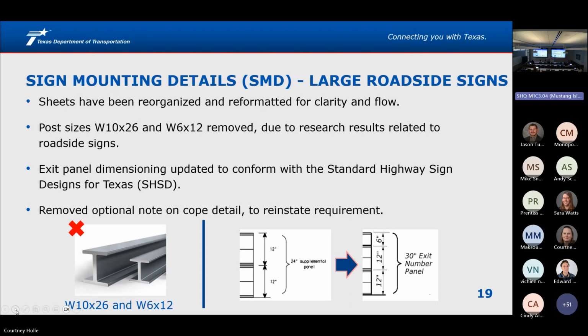Along those lines of signs falling down, we went to the San Angelo sign crew meeting, and along I-10, maybe near Junction, they have a couple of signs where the fuse plate bolts are loosening. About once a month they go out there and retighten the bolts. It'd be interesting to know if anyone else has seen that same thing. We're still trying to figure out whether this new standard of a larger post, possibly a larger fuse plate, will alleviate the issue with the signs falling down.